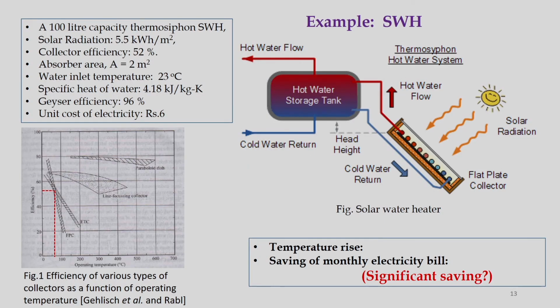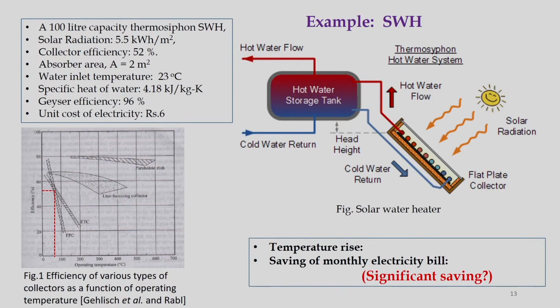Like equating the energy absorbed in the collector during the day to the enthalpy change of the water. So, this is something like solar energy incident, what I will write as IT. IT is the solar energy incident on the collector per unit area per day.